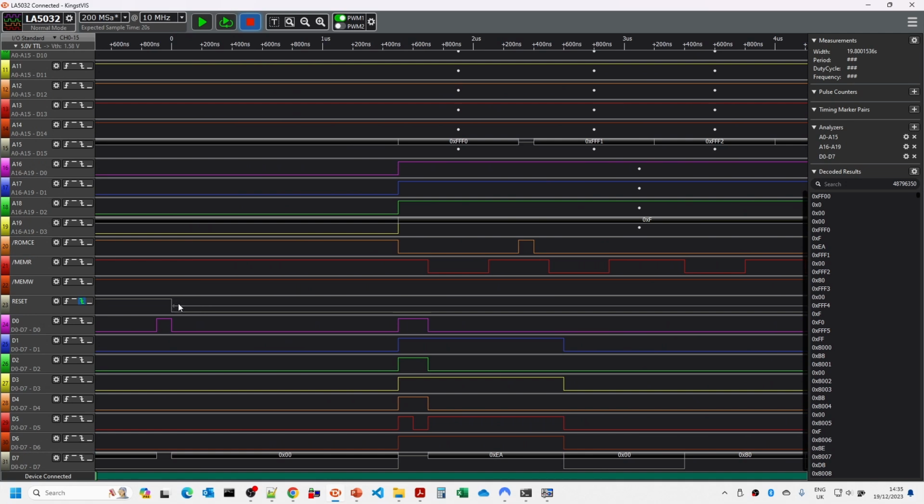After reset, there's normally about 5, 6, or 7 cycles before the processor actually comes out of reset. And what we can see here is the lower 16 address lines, which are FFF0. The top 4 bits are F, so that is our reset vector, the reset location that we expect. And if we look down here, we can even see that the first byte it's reading is EA.